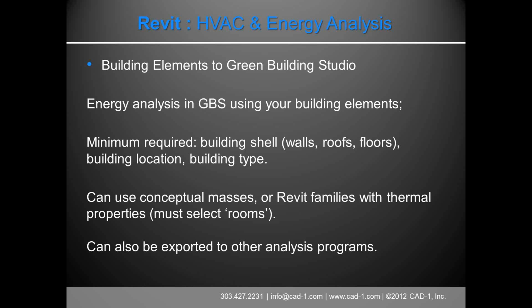Real quick, Tony, a lot of people ask us, why is the building type so important? Well, because the analysis tools put a lot of weight on it. If it's an office, then most offices are occupied primarily between, say, 8 and 5. There's parameters you can set behind the scenes on that, but it makes some assumptions.